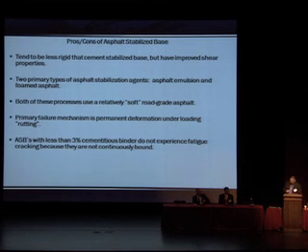Another stabilization technique that's been used, we haven't used it as much in Corpus, but is asphalt stabilization. It maintains a very good amount of flexibility, but it is prone to rutting. It does use a small amount of cement for some strength, but again, we haven't used it as much in our district.